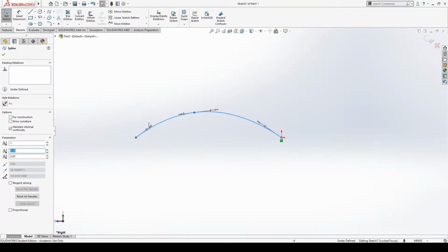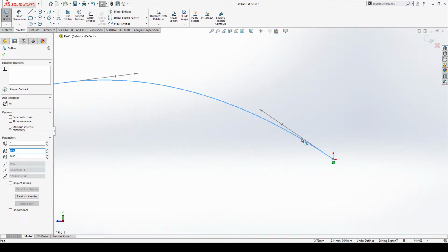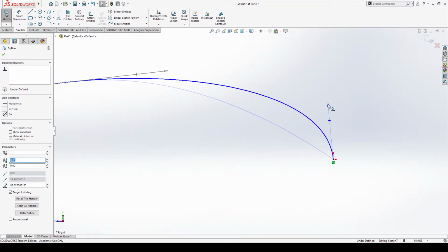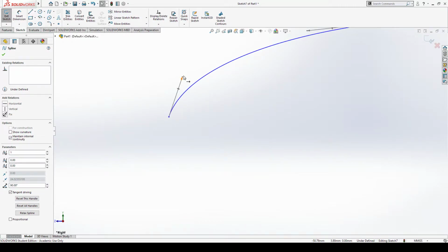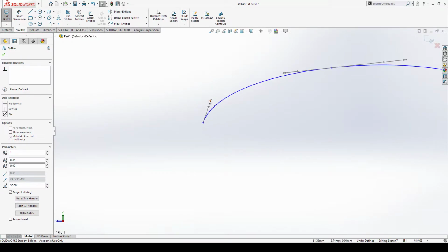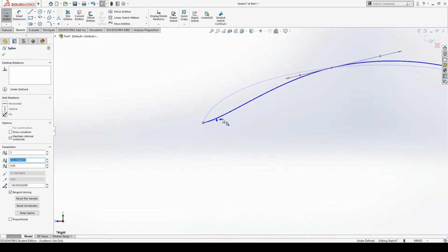There's only 2 rules really with making simple aerofoils using splines, and that's that the leading edge must be 90 degrees, like this. We can set it to exactly 90 down here, and that the trailing edge should be acute. It doesn't have to be acute, it could be straight 90 degrees as well, but in terms of aerodynamic performance, you always want that to be acute.